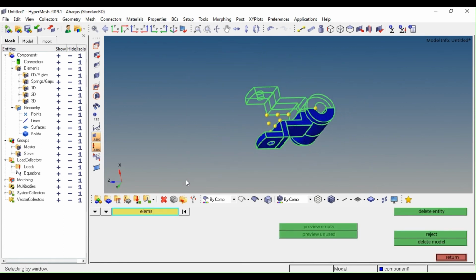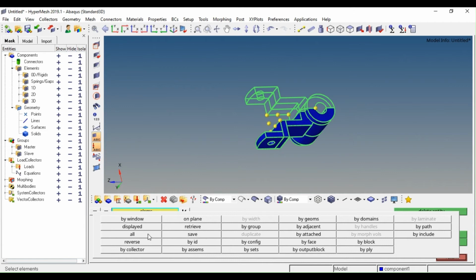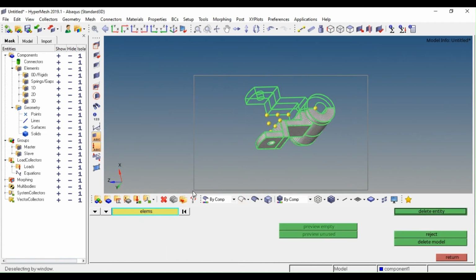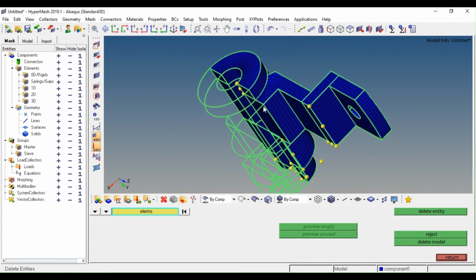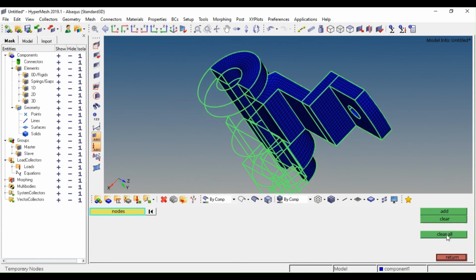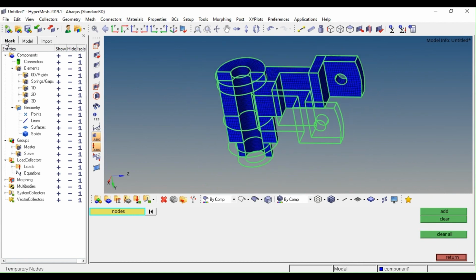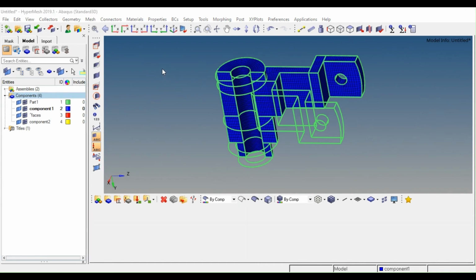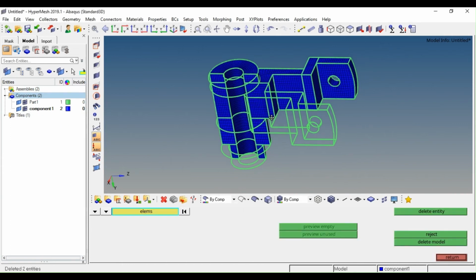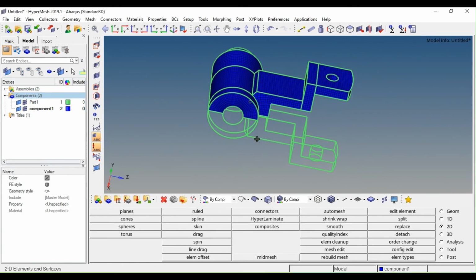That's it. Now I just put here, and now I can just go to unselect, mask these 2D elements and select all, and unselect this 3D element and delete all. So I have just deleted all the 2D elements. I'll clear the free nodes. Okay, now I will unselect whatever is not needed. Okay, these are empty components anyway.